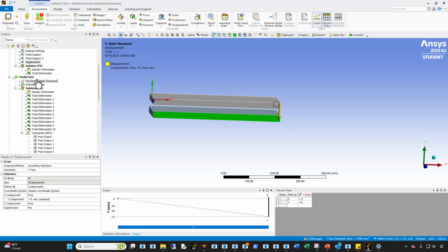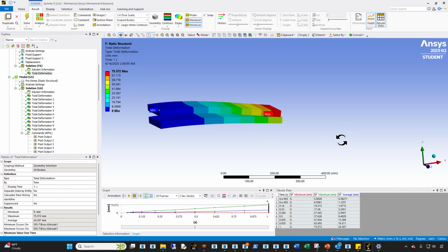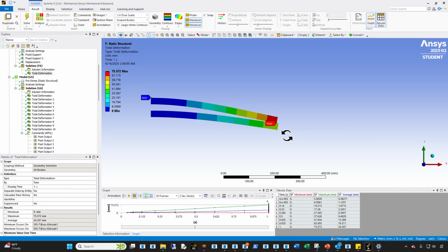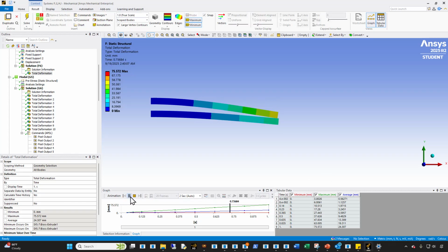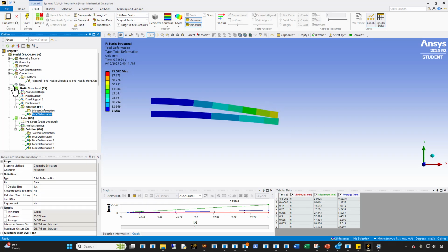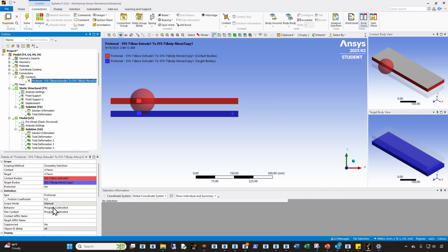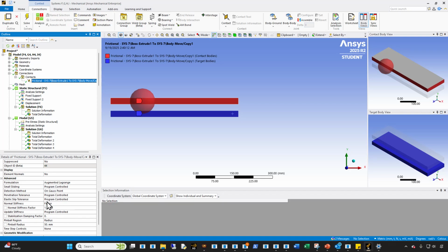And what you get is a situation that looks like this, right? So you have a double deformation that has a contact between the two beams, and that's the behavior I want to be able to model. Now you have to realize, with Mechanical it's very interesting because the penalty stiffness over here I set to be very, very low. There is an FKN factor that I set to be very low to get an easy convergence.